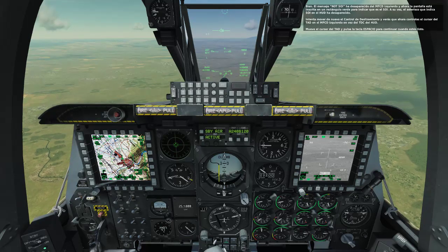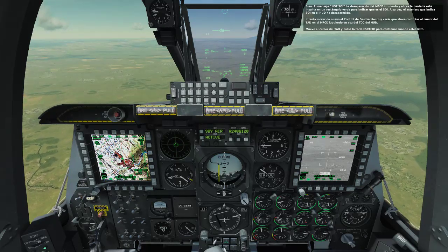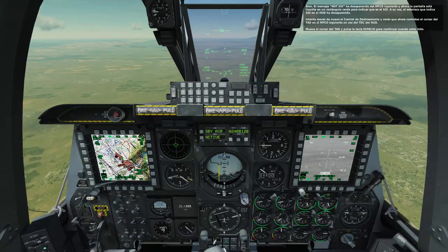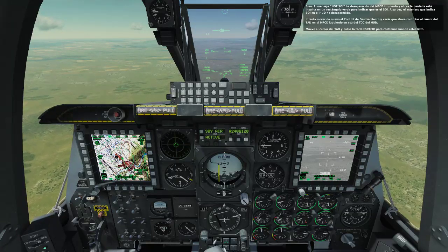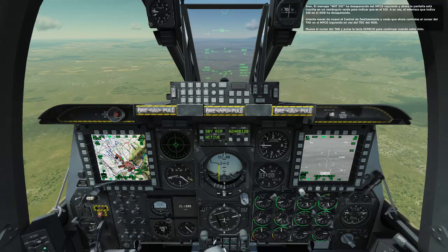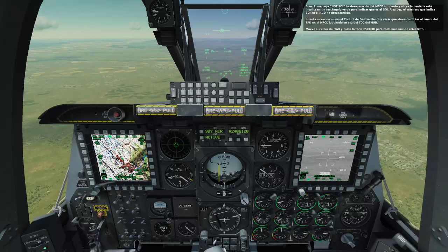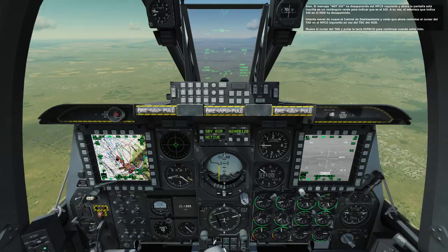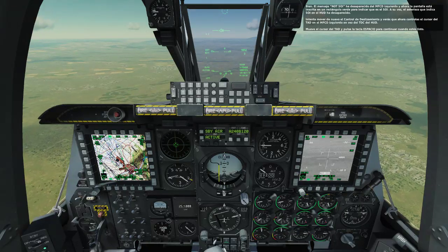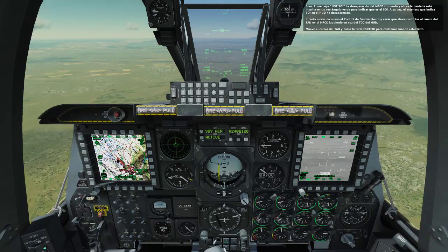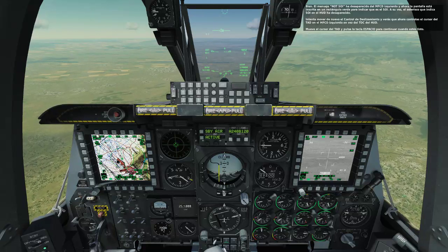Good. The "not SOI" message has been removed from the left MFCD, and the display is now inscribed by a green square to indicate that it is SOI. At the same time, the SOI asterisk has been removed from the HUD. Try again to move the slew control around, and you'll see that you are now controlling the TAD cursor on the left MFCD instead of the HUD TDC. Move the TAD cursor around and press the spacebar key to proceed when ready.